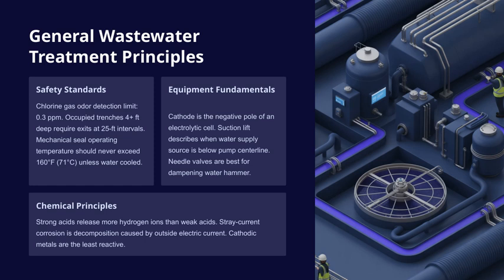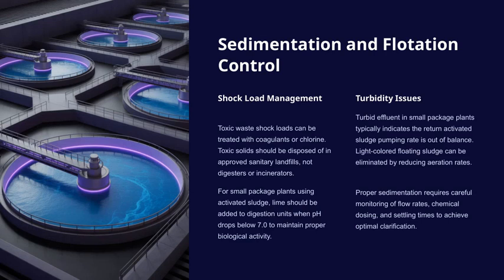Connecting all these points, understanding safety standards, equipment fundamentals, and chemical principles forms the backbone of effective and safe wastewater treatment operations. Today, let's delve into some key aspects of sedimentation and flotation control. First, we'll talk about shock load management. Toxic waste shock loads can be quite challenging, but they can often be treated effectively with coagulants or chlorine. It's important to remember that any toxic solids generated should be disposed of in approved sanitary landfills, not in digesters or incinerators, to prevent further environmental issues.